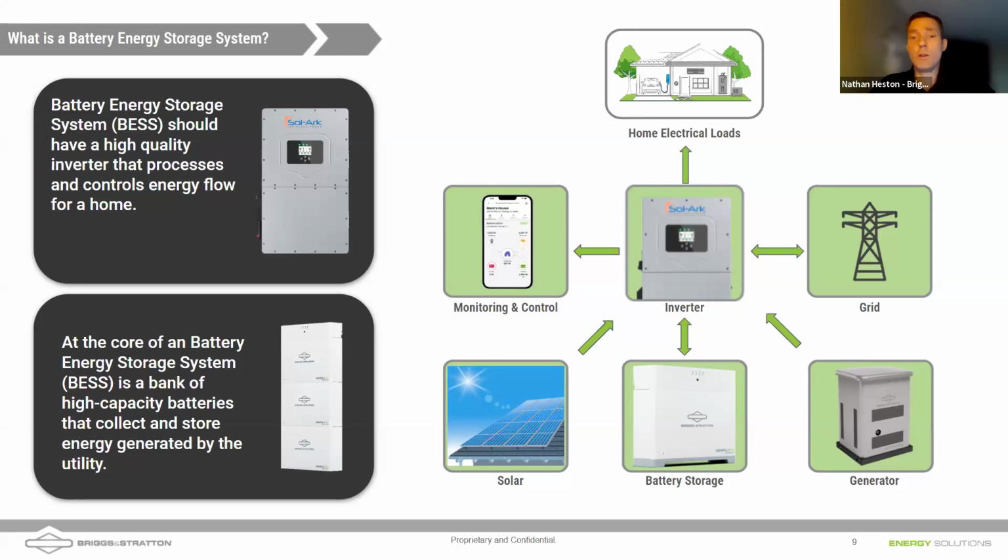Yep. And you could, even without the solar, you could run off that generator, use that to charge the batteries up, and then run on those batteries until the batteries get low, and then start that generator back up again. And in that way, you're optimizing the amount of energy you're getting out of the generator. You can run it at a high efficiency.